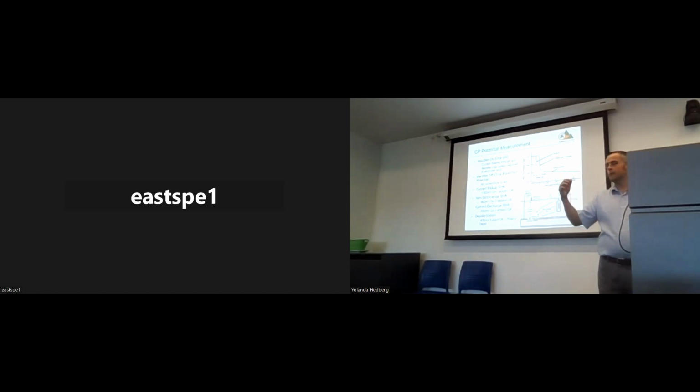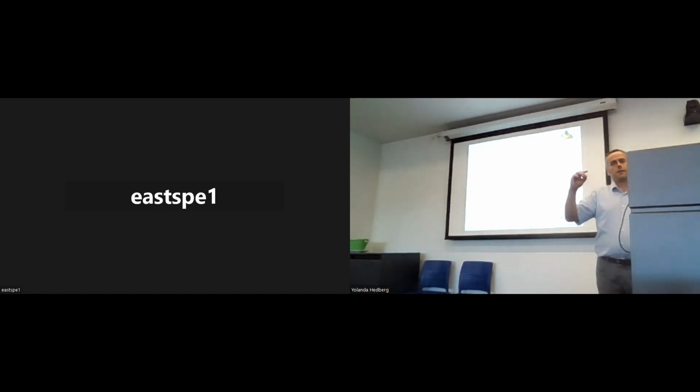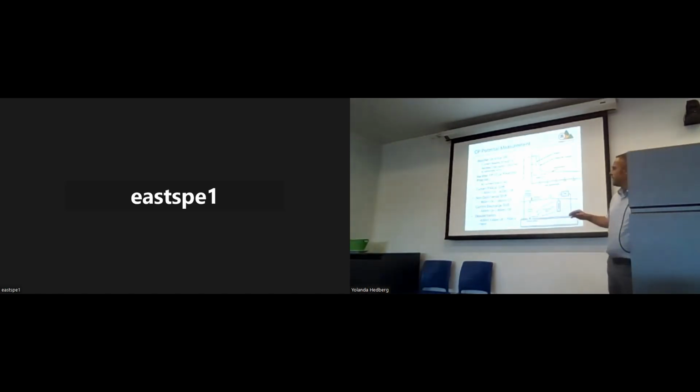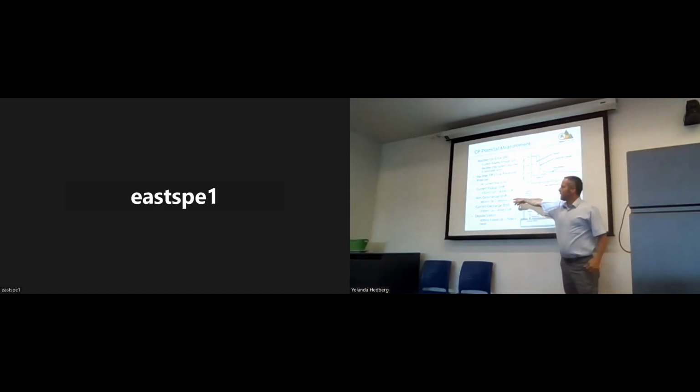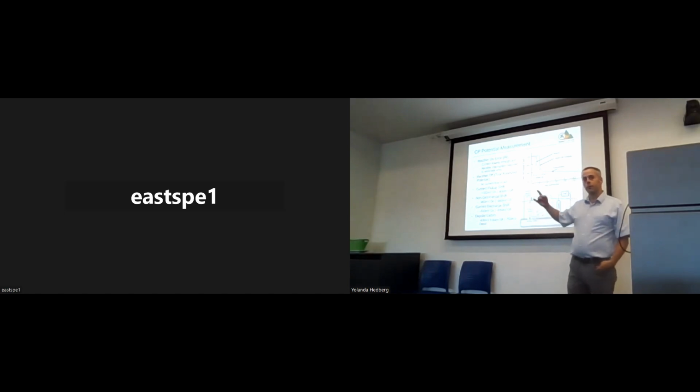Not to get too technical, and I know I've lost some of you, but that doesn't matter, because our off potential is still more electronegative than 850. So we're still achieving criterion. It just tells me that the on measurement to the soil is telling me something different.